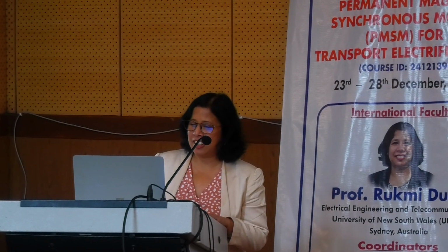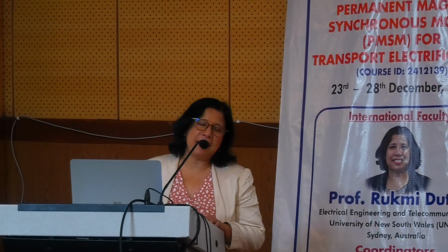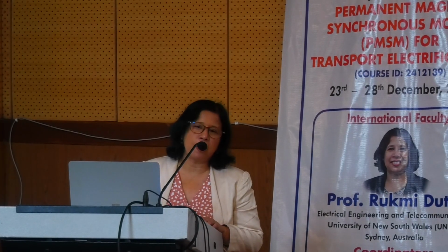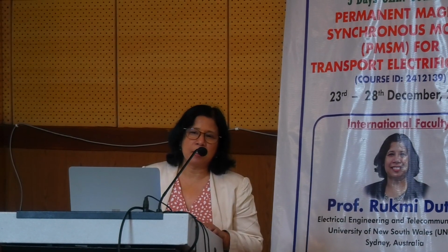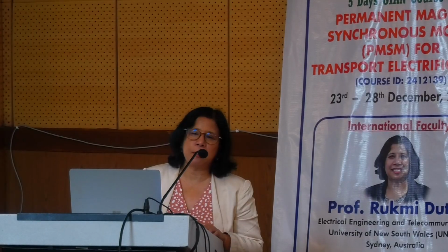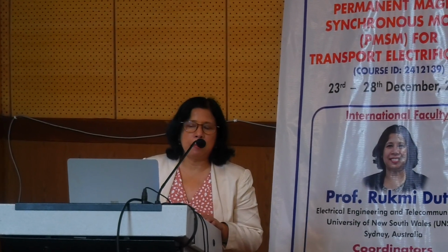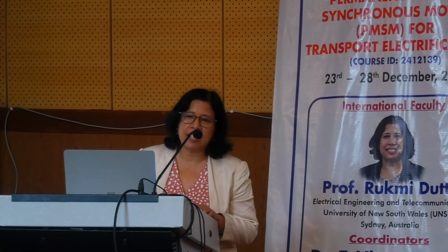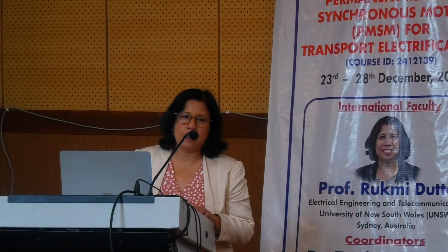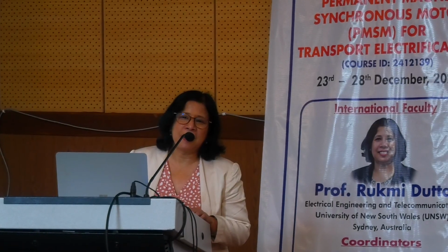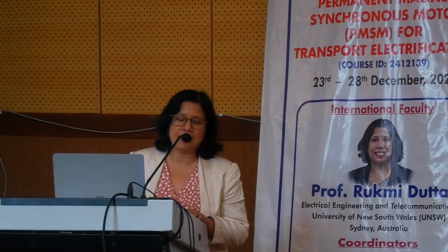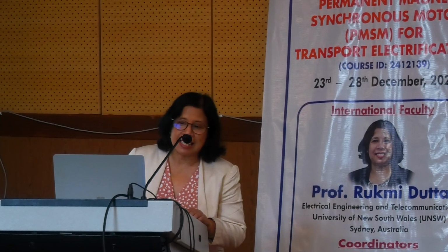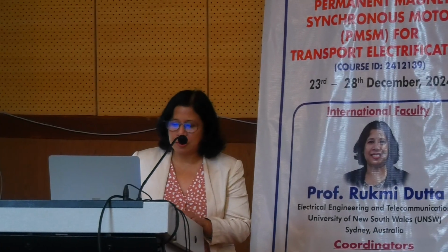Next part of the lectures, there are some very basic concepts. We just want to recall these concepts because, again, they are very important while designing. When we talk about improving reluctance torque or things like that, that depends actually on your Ld, Lq, or inductance, right? So we should recall where these inductances are coming from, and what the synchronous Ld, Lq actually is. We'll try to discuss those things a bit, all right?